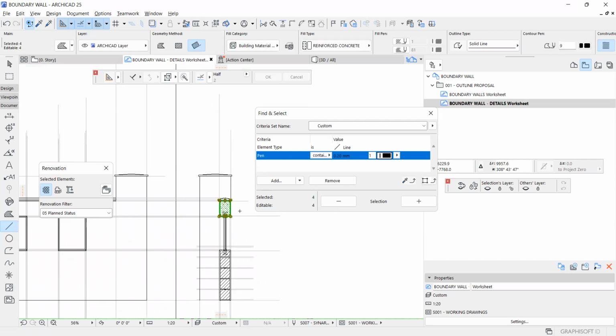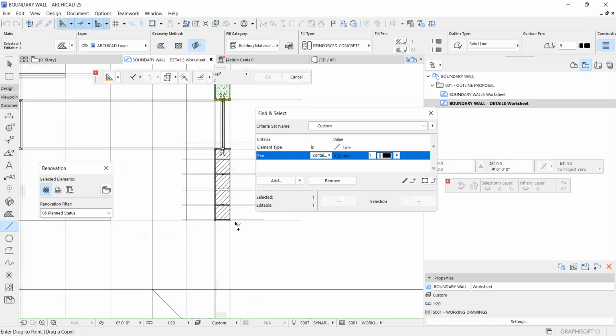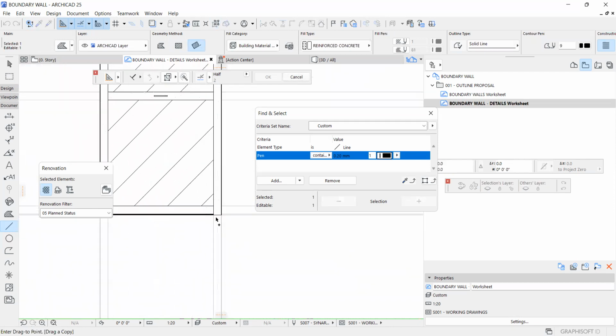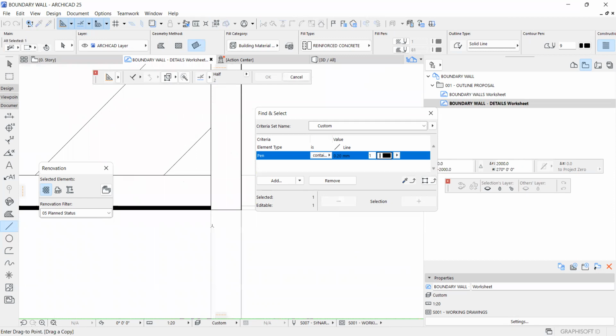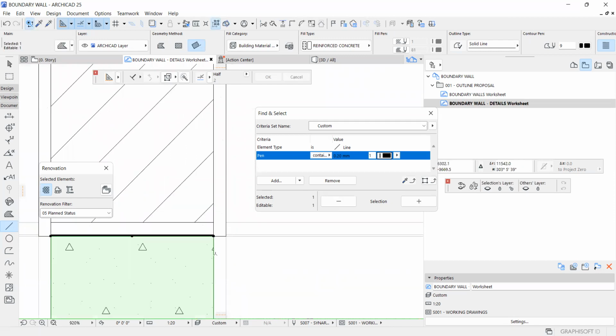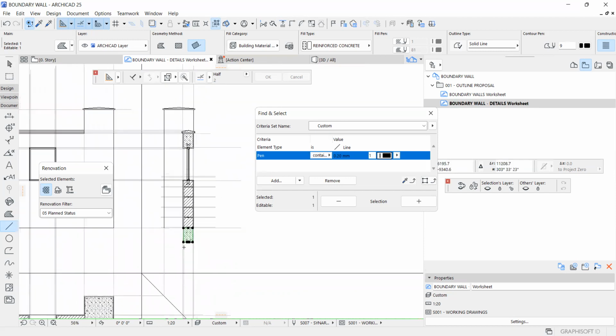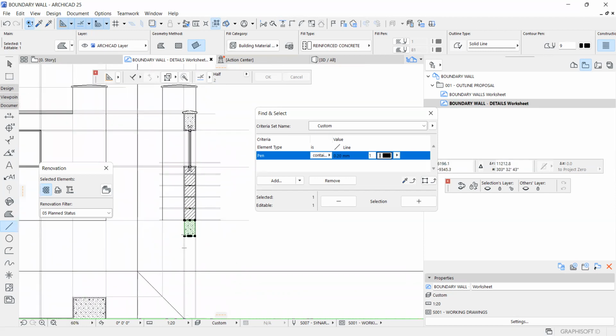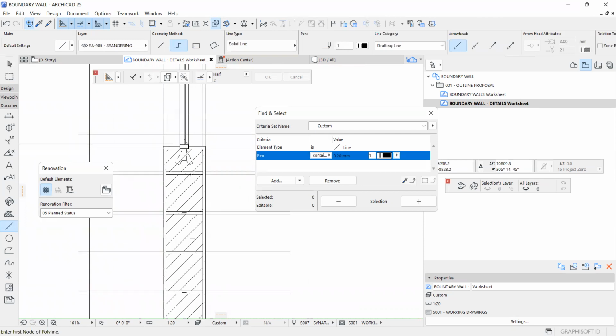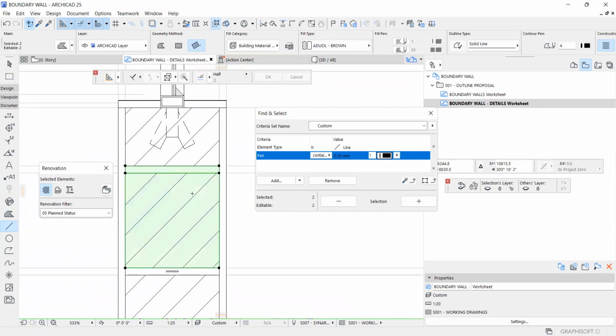Some of us put what we call a ground beam. And since most of this ground beam will be covered on the ground, there will be no need of plaster and paint, okay? And below it, we normally have some few courses of masonry.